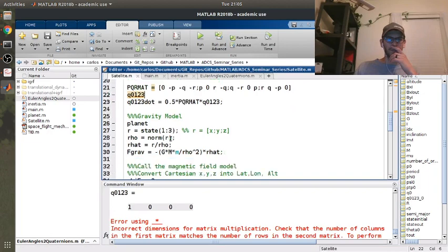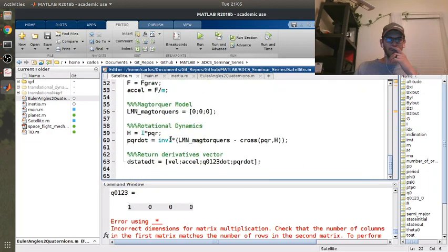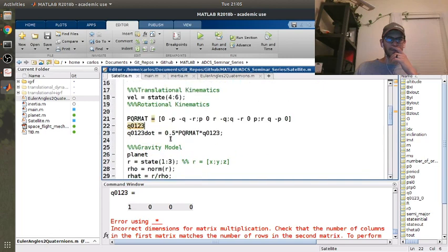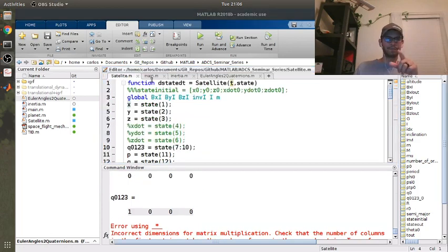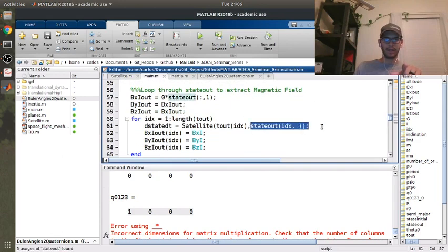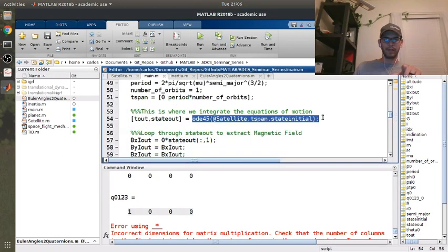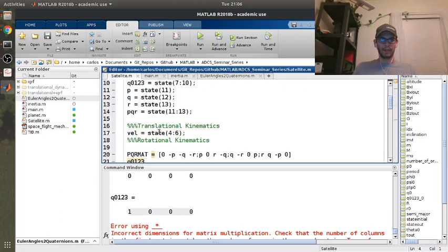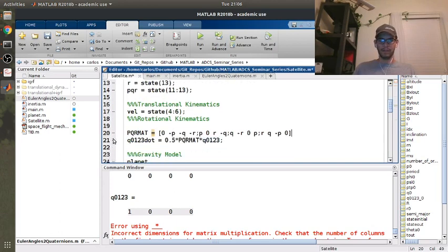Do I pause the video and try to fix this, and then tell you what happened? I'm gonna pause the video and come back. Okay, I figured it out. What's happening is here. So when you run ODE45, this is a column vector, and when you run d state dt, it becomes a row vector. That is a row. So we need to send it the transpose, and then I think I can get rid of this here and this here, and now I can run this.